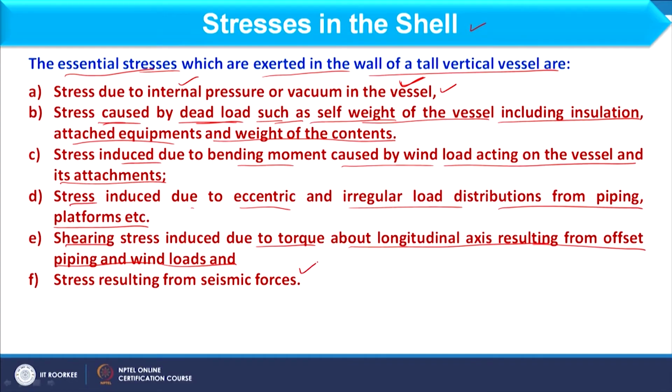And then we have the stress resulting from the seismic forces, because that is the natural condition when we have an earthquake. However, during that condition the vessel should remain standing. So, the stresses generated due to seismic forces or seismic conditions, that also we should include while designing the tall vessels. So, all these stresses we have to count in designing the tall vessel.